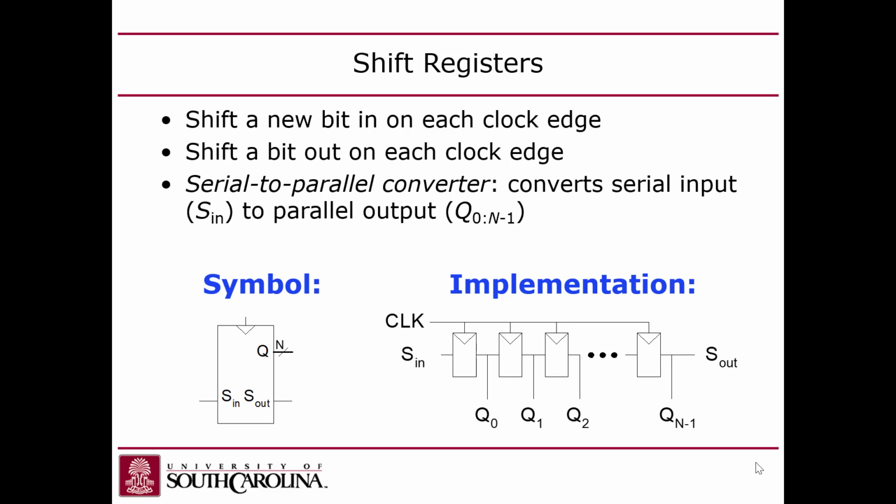There's also this idea of a shift register, which is where you have D flip-flops that are connected in series. So you have one D flip-flop feeding into the input of the next one in like a line. When I first saw this, I was confused. I was like, wait a second, hold on. If you have a circuit like this and there's a clock edge, that clock edge is going to cause all these guys to clock. But if the first one feeds its input through really fast, it's going to immediately get into the second one, and the data is just going to race through really fast on one clock edge.